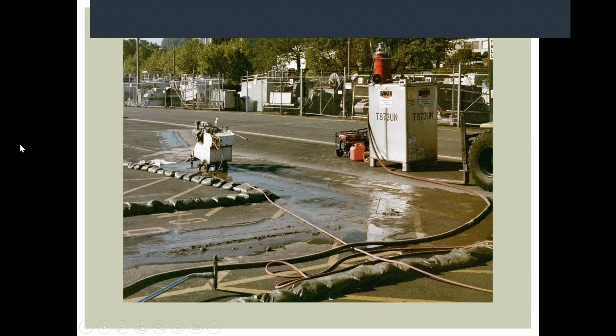Saw cutting, I think everybody's aware of the need to vacuum as you saw cut, so slurry doesn't get driven through or dry out and turn into dust. So this is an interesting one. The city required perimeter controls, and their perimeter control requirement was silt fence. So we had a discussion questioning how you install silt fence on asphalt, and they agreed that sandbags would be a good perimeter control for this.